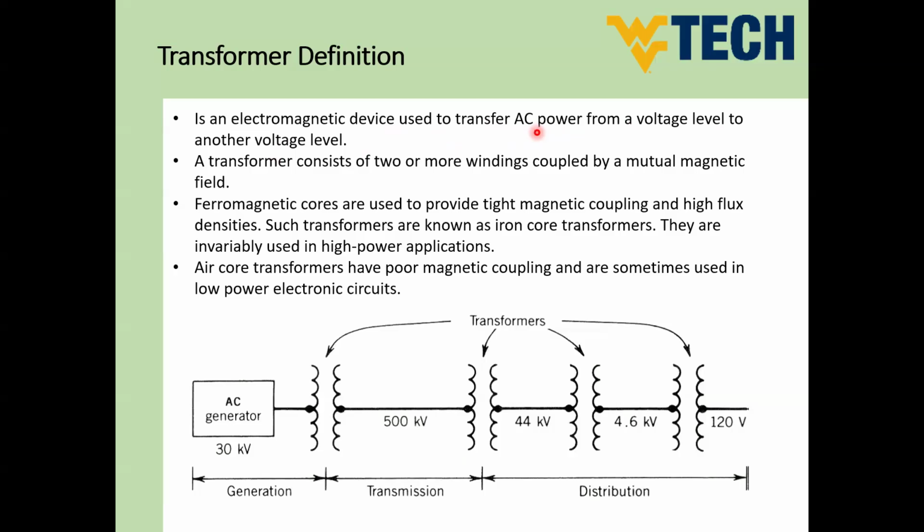However, if you make some modifications for the DC to make it variable, then in this case you can use transformer. If you take the power electronics class, you will learn one of the topologies of DC power supply. It includes a transformer called push-pull transformer, so it can transfer DC, but only variable DC, not pure DC. However, in general, we can refer to transformer that it can transfer AC power, not DC power.